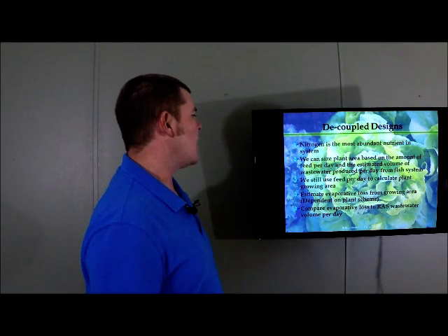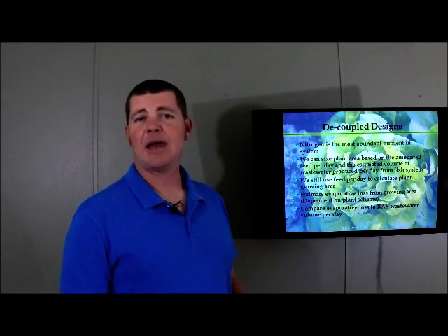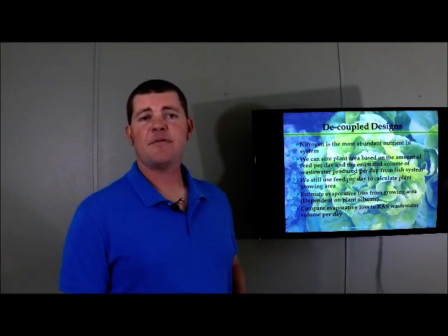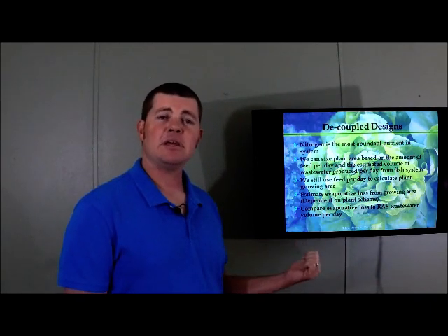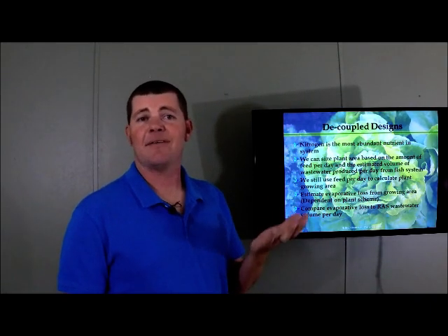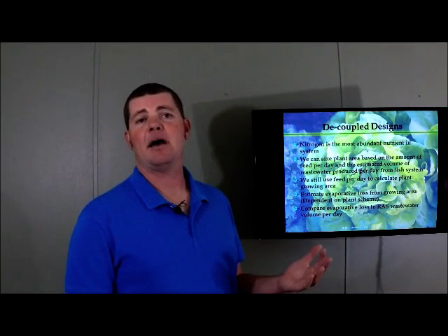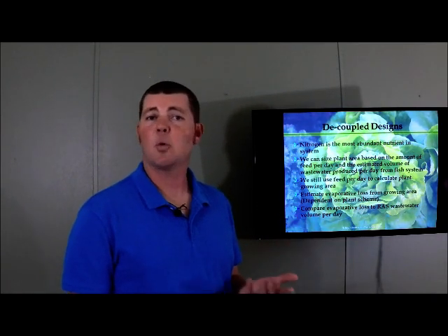Compare the evaporative loss to the RAS wastewater volume per day, and that's how you figure out exactly what you have to do. If it's perfectly matched, guess what? You don't have to do anything. If you have more wastewater coming out than you have room for in the hydroponic area, you need to evaporate some of that water. And vice versa, if you don't have enough wastewater to fill up the hydroponic area, you're going to top it off with fresh water.